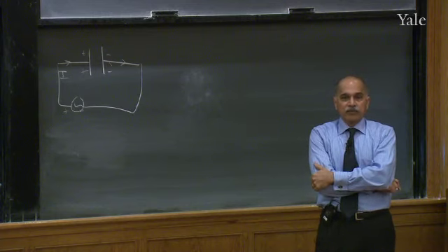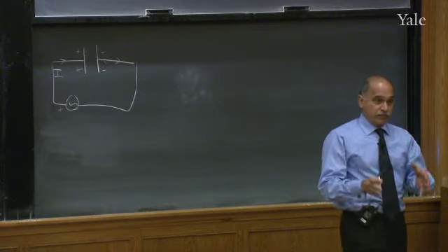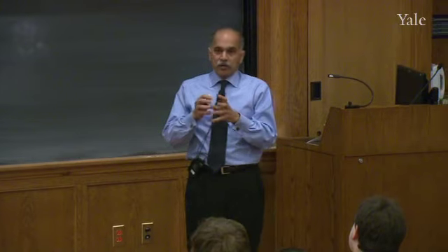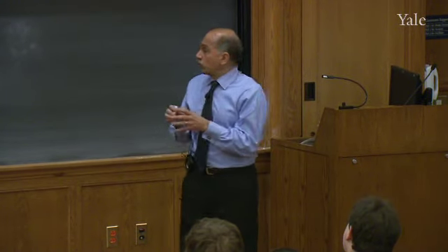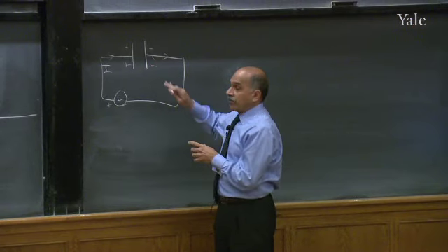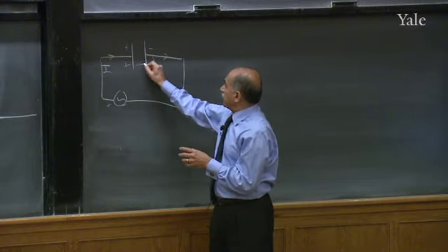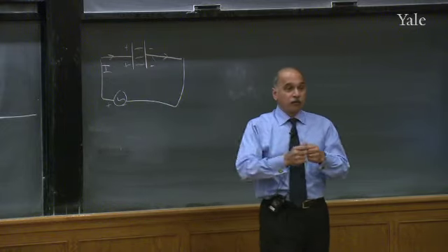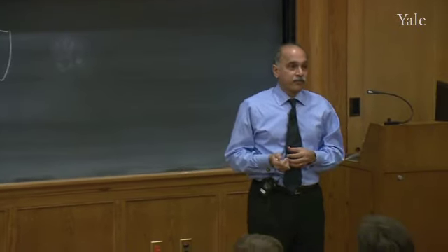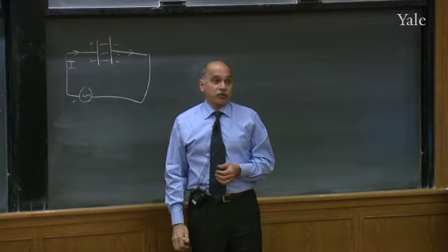It'll jump the gap if here's what happens. Depends on what's in the medium. If you put air, for example, the air molecules are all neutral. So there is no way for the plus charges to ride them and go to the minus terminal. But if the electric fields, this will certainly produce electric field, are so strong that you rip out the plus and minus charges, then suddenly you've got a bunch of free carriers. Then the minus charges can immediately go and neutralize this one, plus can go and neutralize that one.